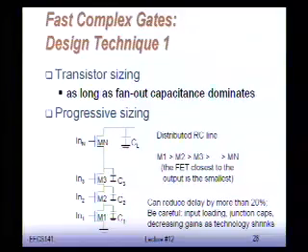It turns out this is a really good idea in theory. In practice, it doesn't work as well because if these devices have different sizes, you can't really share the junctions. So your layout gets more complicated. Because you can't share the junctions, you add more parasitics. So you did all these things to get smaller delay, but you are adding capacitance, which also increases the delay. Also, the area is bigger because, again, you can't share as much. So it turns out this gives some 20% improvement, but it might look a little better on paper than it does once you actually implement it, okay?